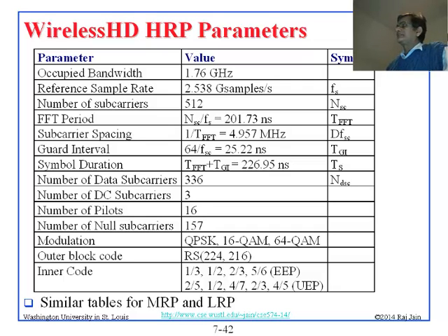Basically, there is no signal sent on that one, and so there is a gap there, and with the gap you can figure out that this is where the middle is, and this is where my first, second, third, fourth, fifth, sixth subcarriers are. Right? So that is null, but they have 3 DC carriers. So they take not only the middle but also the next 2, and those are sent as zeros. I mean, there is basically no signal on those 3. There is no signal on 157. 16 are used for estimation, so that leaves 336 data carriers, right?